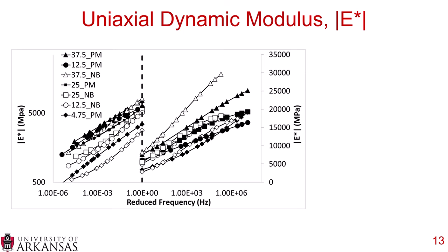And then on the right side is the higher dynamic modulus values, which is at the lower test temperatures and higher frequencies, which kind of make you start thinking about what happens at the lower temperatures, so the stiffness of the mixture at those lower temperatures and higher frequencies.